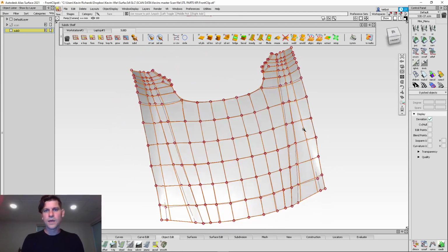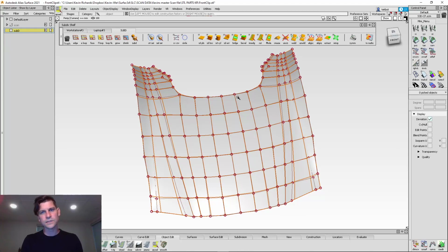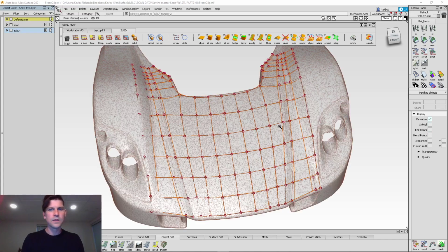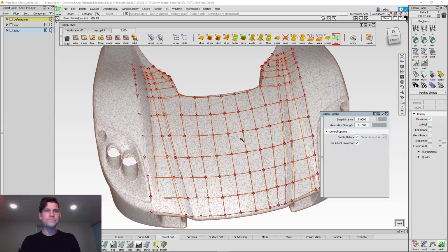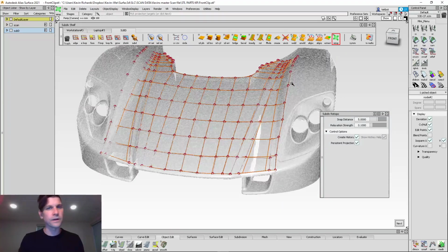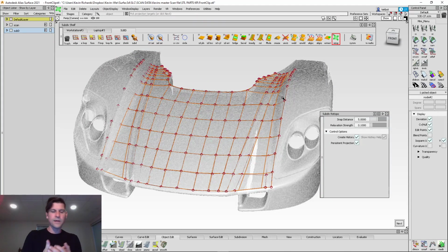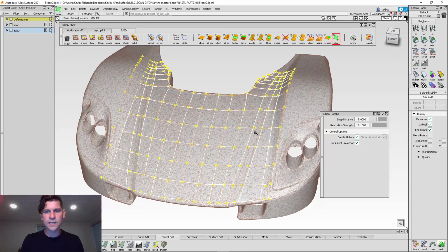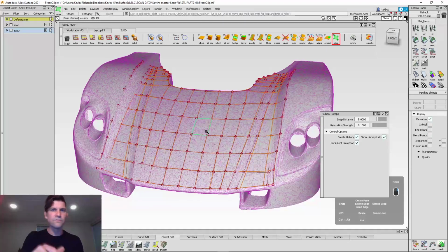Just like that. And this is a good example. So I just welded those and it deleted the retopo features of this mesh. And so I believe, let's just try this out. If I go into the tool, it'll ask for the projection target. This is like the destination if you're using the dynamic shape modeling tools. Yeah, this is what we're going to be modeling on top of. I'll hit next, and then I'll grab the sub-D that I want. I'll hit go, and now it just converted that to work with the retopo workflow.